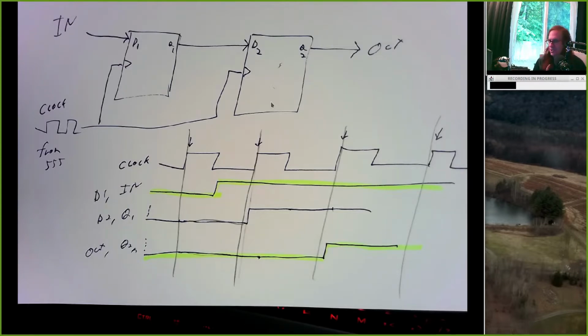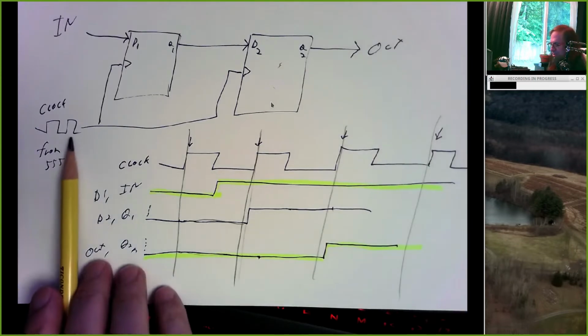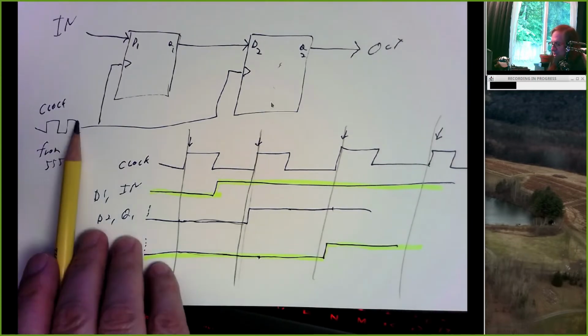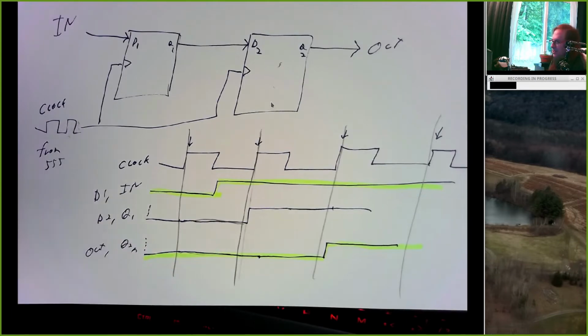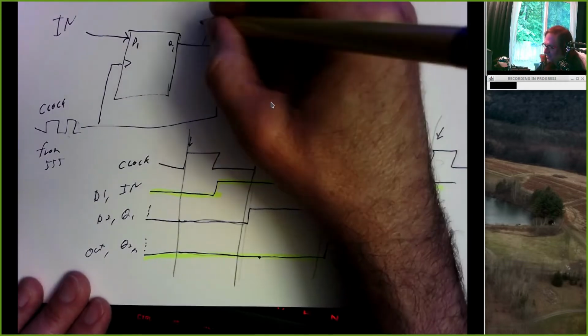So if your circuit is not doing that, what should you do? Make sure that your clock is changing slowly. Put an LED on whatever this line is and make sure it blinks on, it blinks off, about 2 seconds per cycle. That's the first thing, because if this clock goes really fast, this will appear to happen instantly. Assuming the clock is changing correctly, put an LED on this.